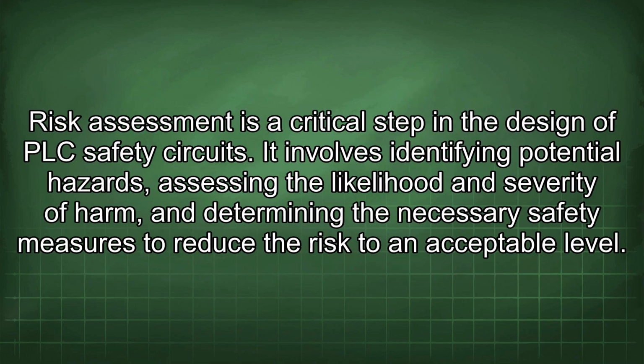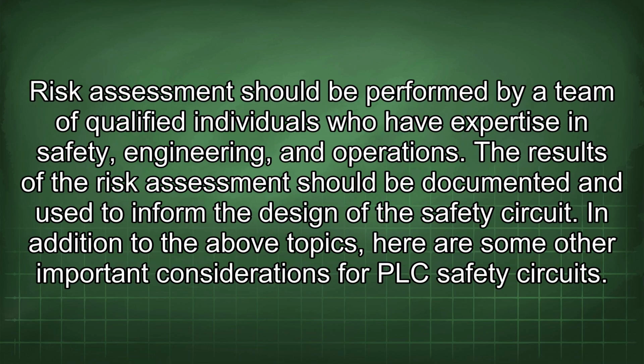Risk assessment is a critical step in the design of PLC safety circuits. It involves identifying potential hazards, assessing the likelihood and severity of harm, and determining the necessary safety measures to reduce the risk to an acceptable level. Risk assessment should be performed by a team of qualified individuals who have expertise in safety, engineering, and operations. The results of the risk assessment should be documented and used to inform the design of the safety circuit. In addition to the above topics, here are some other important considerations for PLC safety circuits.